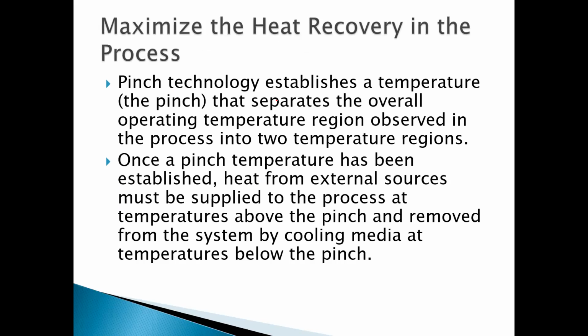We do this by pinch analysis, pinch technology. We construct the pinch diagram, we find the pinch point, pinch temperatures, minimum heating utilities, minimum cooling utilities. Once we set the energy target, which is the minimum utilities requirement after the integration, we can go and develop the design, the excellent design of the process.